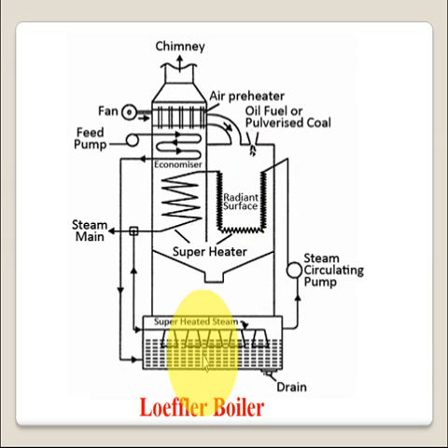And the disadvantages of the Lamont boiler are overcome here because the water is not evaporated in the tube. In this case, water is evaporated in the drum and only steam is circulated. So the salts dissolved in the water get collected in this evaporator drum, and we can drain out the sediment or salt associated with water. And this overcomes the drawback of the Lamont boiler as well as the Benson boiler.